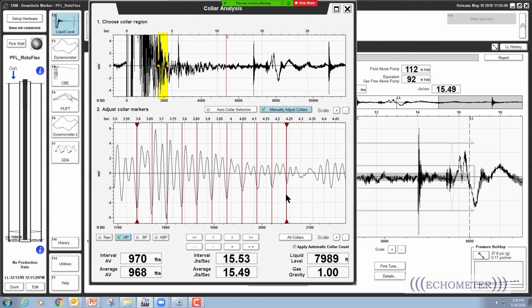So if I have a gas gun, the type of gas gun is going to determine how you shoot this well with 1,000 pounds of pressure. So normally when you have 1,000 pounds of pressure, if you have a remote fire gas gun, that means you're going to have to charge your gas gun with nitrogen pressure and do an explosion shot. The remote fire gas gun mechanism inside the gun doesn't allow it to do an implosion shot. So you're somewhat restricted, and the working pressure of the remote fire gas gun goes up to 1,500 psi. So that's going to be the maximum pressure that you could typically charge your gas gun to and be within the working pressure of the gas gun.